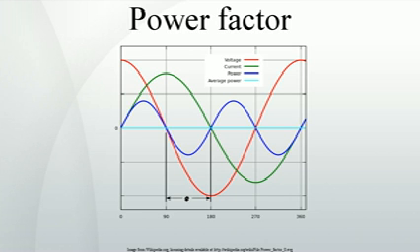Dynamic PFC. Dynamic power factor correction, DPFC, sometimes referred to as real-time power factor correction, is used for electrical stabilization in instances of rapid load changes. When electrical networks experience rapid load changes, especially with the presence of nonlinear loads, standard power factor correction is unable to adjust to the constantly changing, that is dynamic, electrical network, causing over or under correction.